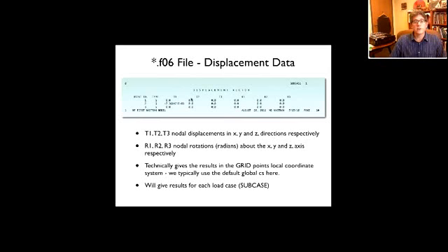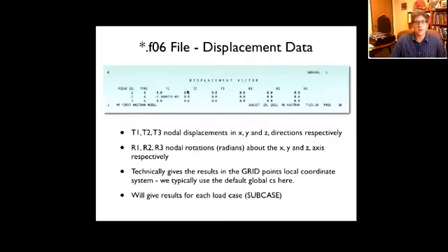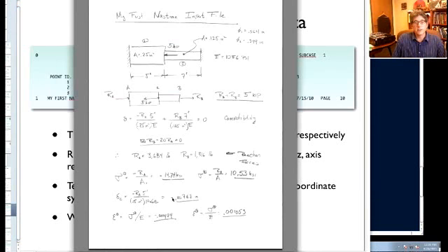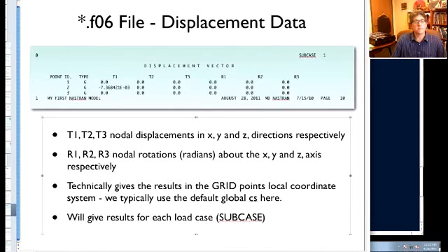Okay, so here you can look at the displacements. In fact, here you can see all the displacements are 0 except for the x displacement at node 2, and it's minus 0.00737 units, and that actually corresponds directly to the exact solution. If we go back to the exact solution, where's the exact solution? Here's the exact solution. You can see the displacement is minus 0.00763 inches. Okay, so this is why you want to check those values. All the other displacements are 0.